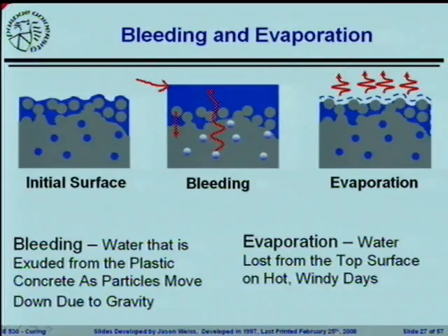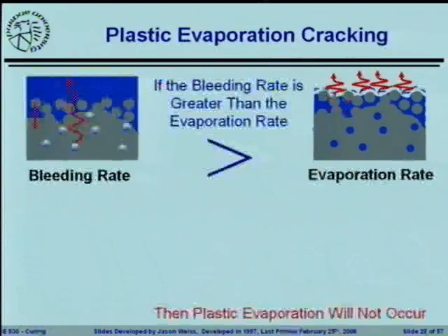The basic idea here is this water is there. It will evaporate off. If it evaporates off, it's essentially just taking water away from the surface and not really drawing the water out of the structure of the concrete. If the evaporation rate gets too high, though, you'll start to see this water front receding in between the particles, and there you can start to have a problem, because you're generating a very high underpressure in this pore fluid, and that high underpressure could result in cracking.